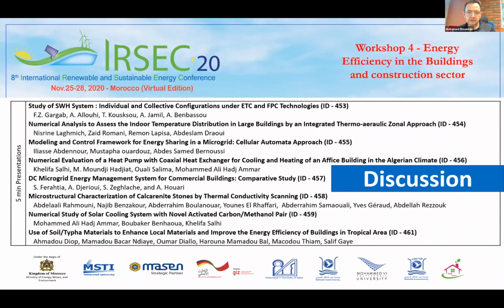It's like triple glazing or something like this for insulation. You're right, but under Moroccan or Mediterranean climates, super insulation is not very much needed, and it could even be harmful for the performance of the building because, as you mentioned, it can lead to summer discomfort, overheating, and so on.